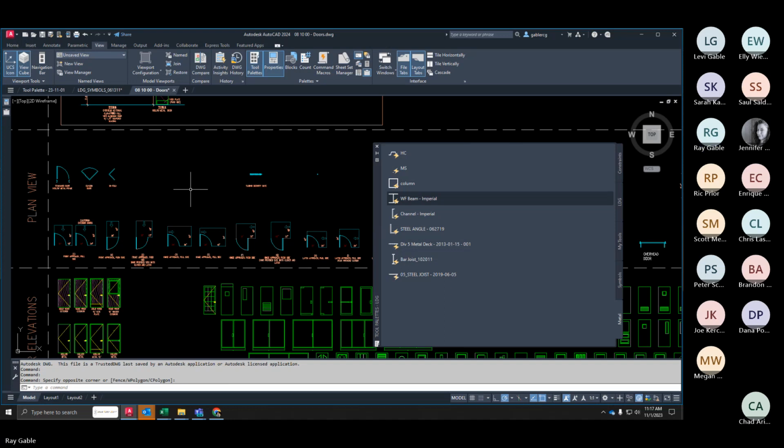And then another one that I actually like is the plumbing one. You know, you primarily use 3 fixtures. I mean, you don't need to take it down to the Toto, Kohler or any of that. You know, basically you need a floor mount with a flush valve, floor mount tank, or wall mounted with flush valve. I mean, that's what they're going to do. They're going to take that, look at that and have a good understanding of it, but to get to the specifics of it, there needs to be some sort of spec or schedule presenting that data to the GC, because they're not going to be able to tell that from a CAD file really. So that's another one that I like in there too as well.